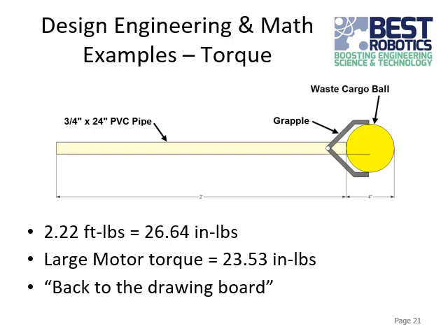Maybe you could make it shorter so that it doesn't need to lift as much, like out as far away from it. That'll reduce your torque. Maybe there's something you could do to make your gripper lighter, or make the PVC pipe lighter by drilling a few holes in it. But then you have to make sure that you're not going to jeopardize the structural integrity of it.